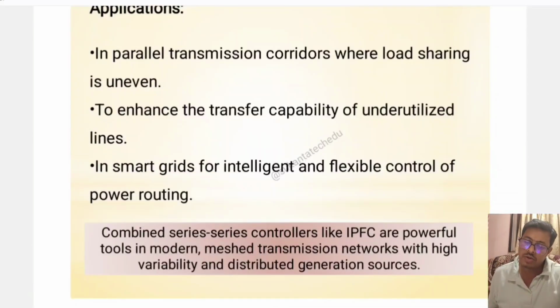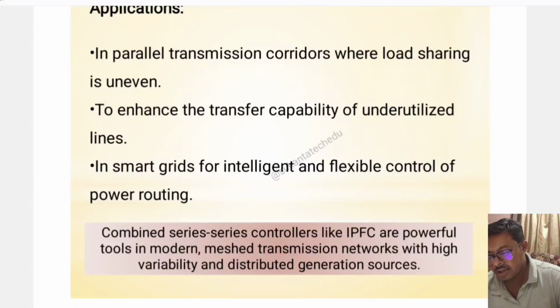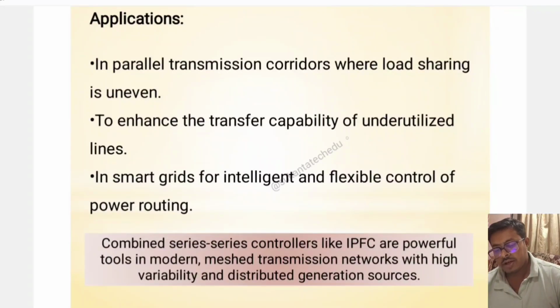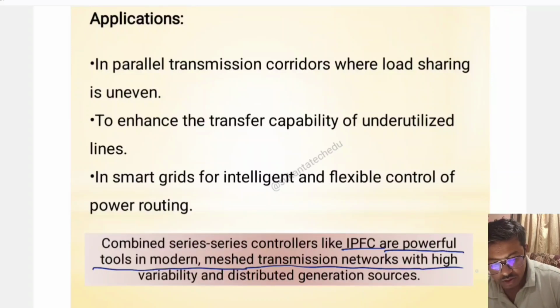In parallel transmission line corridors where the load sharing is uneven, we can use this series controller to enhance the transfer capability. We can use this series controller in smart grids for intelligent and flexible control of power routing. Combined series controllers like IPFC are a powerful tool in modern mesh transmission networks with high variability and distributed generation sources.